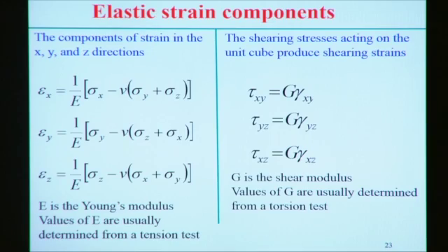If you look into all these expressions, the positive amount of strain comes from the individual stress component along that specific direction, positive in the sense that sigma x, sigma y or sigma z are all positive. At the same time, the negative contribution comes from the other two components of the stress when we focus on one specific axial direction.